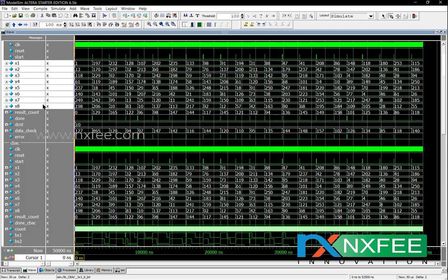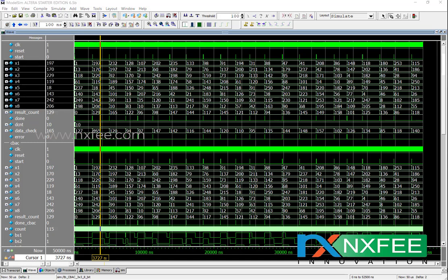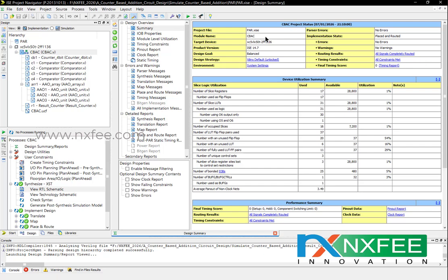In the 3x3 image processing architecture, all the 8 pixels are taken for a mean value, and the mean output is placed at the center pixel. It supports applications such as image denoising, pre-processing for computer vision, medical image processing, satellite remote sensing, document image processing, and video processing. All these processes support the 3x3 mean filter, to obtain the 9th pixel value. This work we have synthesized on a Xilinx Virtex 5 FPGA.